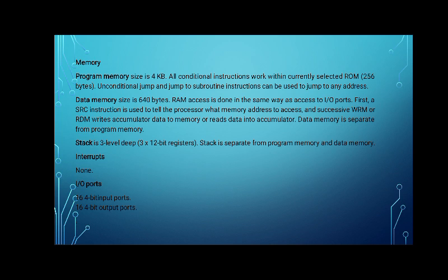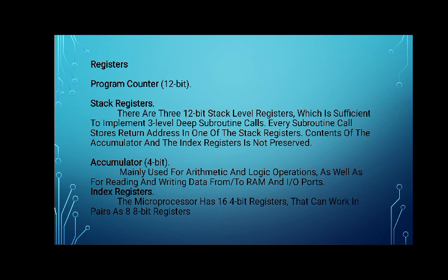Here there are 16 4-bit input ports as well as 16 4-bit output ports, so the output and input ports are 4 bits in size. The registers here are the program counter registers, stack registers, accumulator, and index registers. These are all the same as the modern day registers.